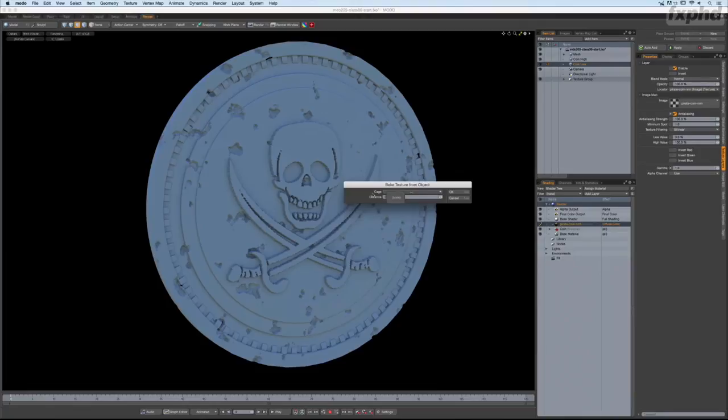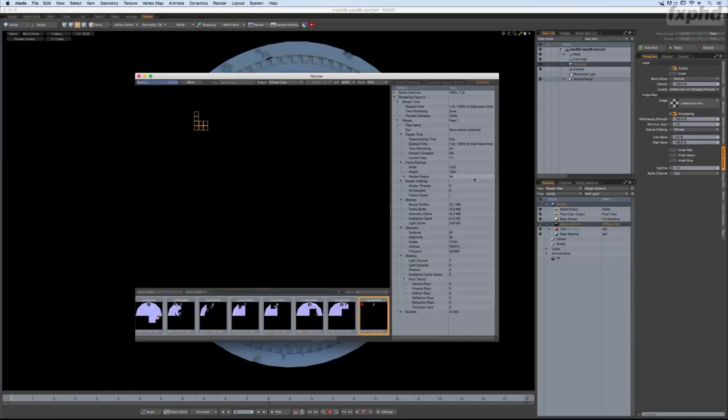And we're going to talk about this cage here in a second. Leave the distance at 0 and just hit OK. And let's just see what we have. Now, the computer's going to fire off a whole series of rays from the surface of our geometry, and it's going to capture all of the information that it interfaces with inside of our system.